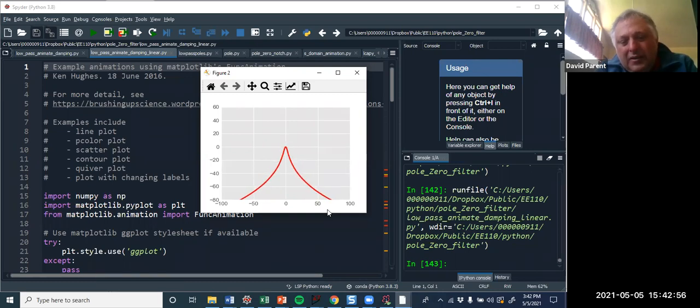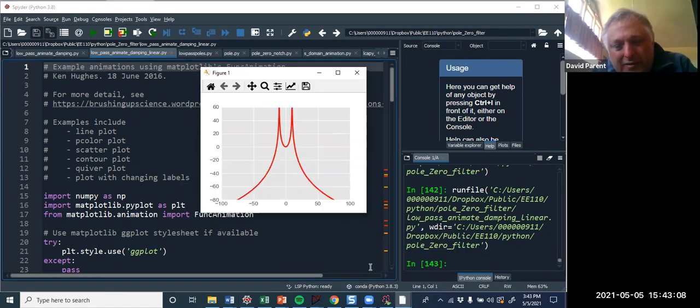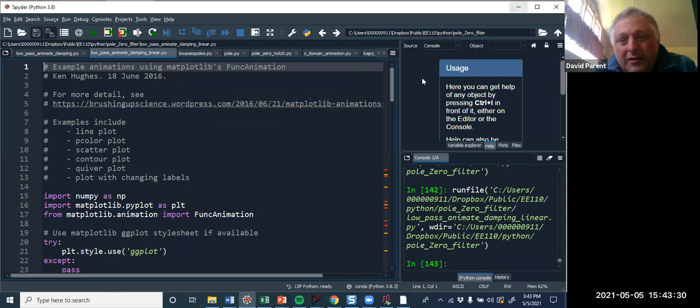Actually, this is linear, it's not in dB, otherwise it would look like a Bode plot. So really, this is both sides. And if I only took this part and excluded 0 and took 20 log of it and put this on a log scale, I'd get back the Bode plot. And sometimes in modulation, you need to talk about the fact that there's this negative and positive frequency. All right.